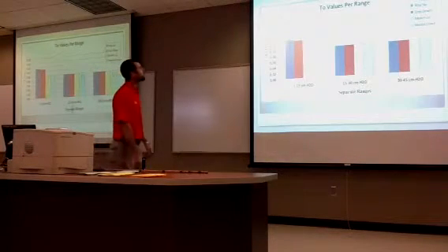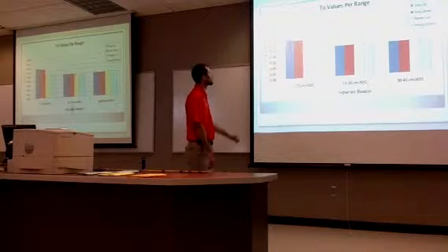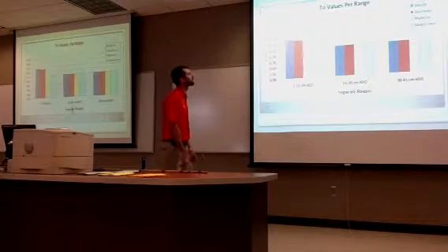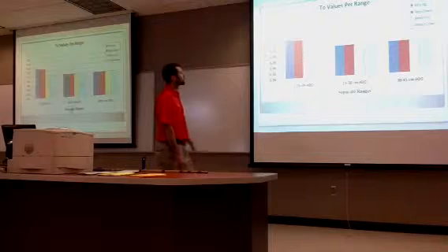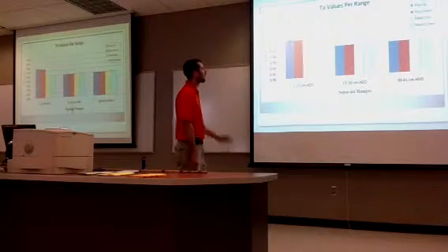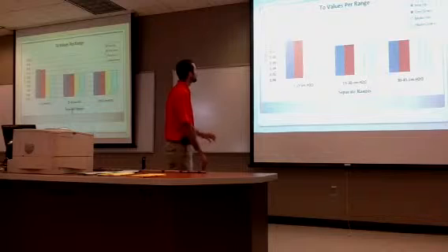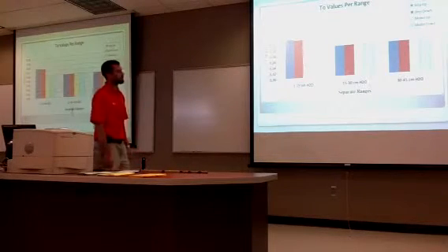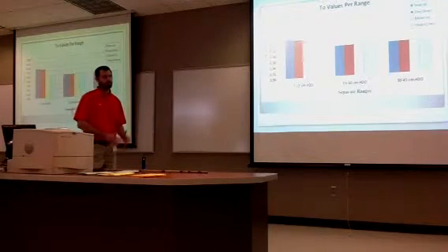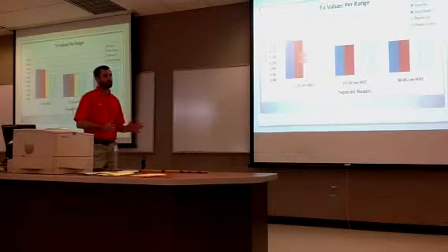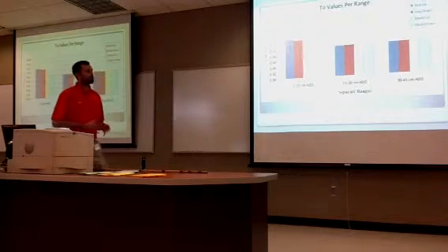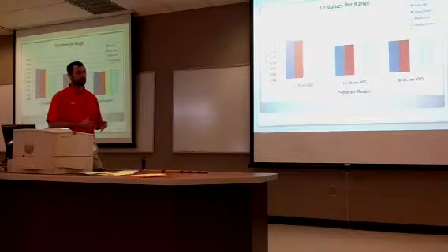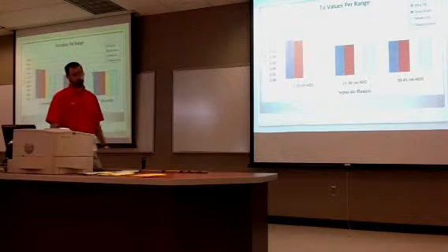These are our T-naught values for 1 to 15 centimeters of H2O, 15 to 30 centimeters of H2O, and 30 to 45 centimeters of H2O. We were consistent within the range, the upper and middle range, but we did have one deviation in the lower range, and we think it's due to system functionality. It performs within the mid to high range and doesn't have the capability of reading the actual inputs and outputs on the lower end.